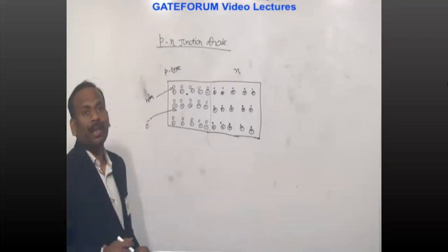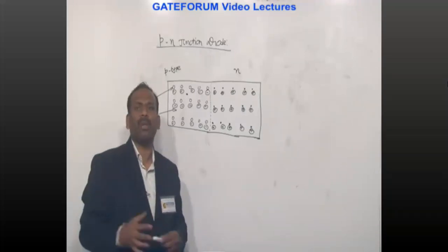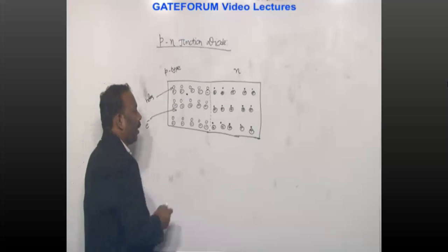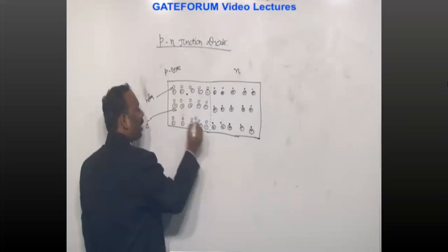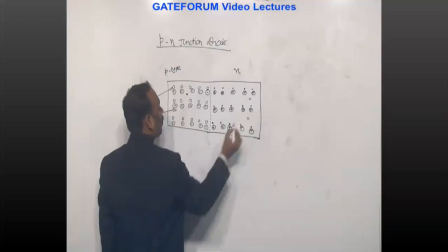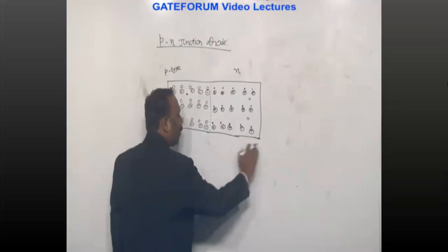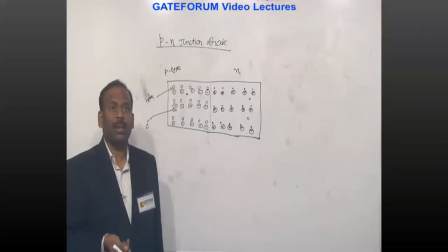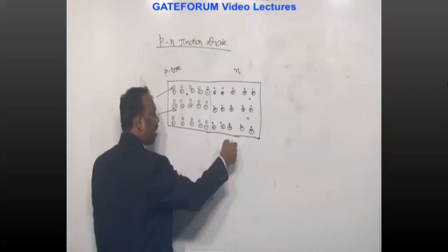Now what is going to happen? Once you have added p-type impurities on one side and n-type impurities on the other side, what happens next? See here, we have holes, here we have electrons. If you see, there are more holes here and fewer holes here. So a concentration gradient of holes exists. High concentration here, large number of holes, here fewer holes.